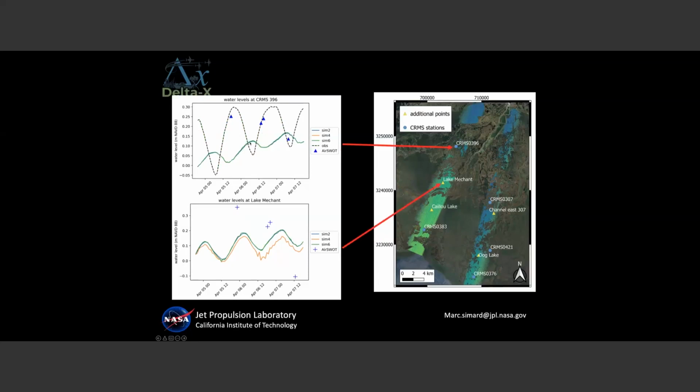So we have to play with the model parameters, so bathymetry and friction, so that the observations fit. So it seems like the tide doesn't make it all the way up north in the simulation. So we have to correct that. But again, the remote sensing here keeps the model real, so we're working on that.